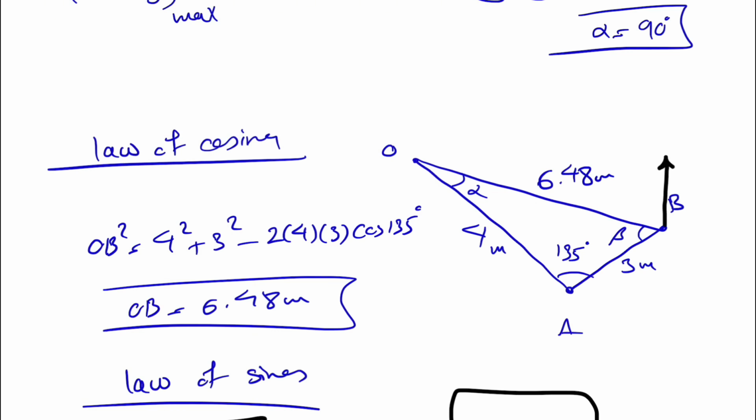So now that we have that, let's go over the two scenarios that we can get the maximum moment. So one of them was this one when we have our 8 kilonewton here, and the other one was this one. And each of them, this force is perpendicular to this one, and here we have the same thing. They're both perpendicular to our OB. So one of the theta that we have in here is this one, which we call theta 1, and the other one is this theta, which we can call theta 2.